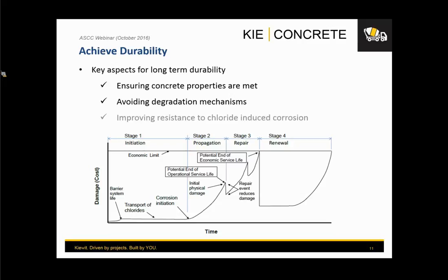Then obviously, something that we look at a lot, because it's something that is evaluated a lot when you're talking about long-term durability, is providing resistance to avoid chloride-induced corrosion, right? We know that we're dealing with reinforced concrete, and that we need to consider what are the strategies to protect the concrete for that, right? You need to look at the mix. You need to look at the surface treatments. You need to look at the cover of your rebar. You need to look at the type of rebar you're selecting to use, right?